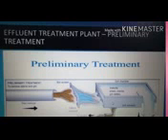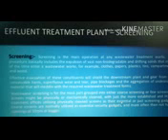In this preliminary treatment, the aim is to remove the debris and grit from raw sewage. There is a bar screen for debris removal, and in the grit chamber the velocity slows and coarse grit settles. Grit is removed and finally goes to landfill.